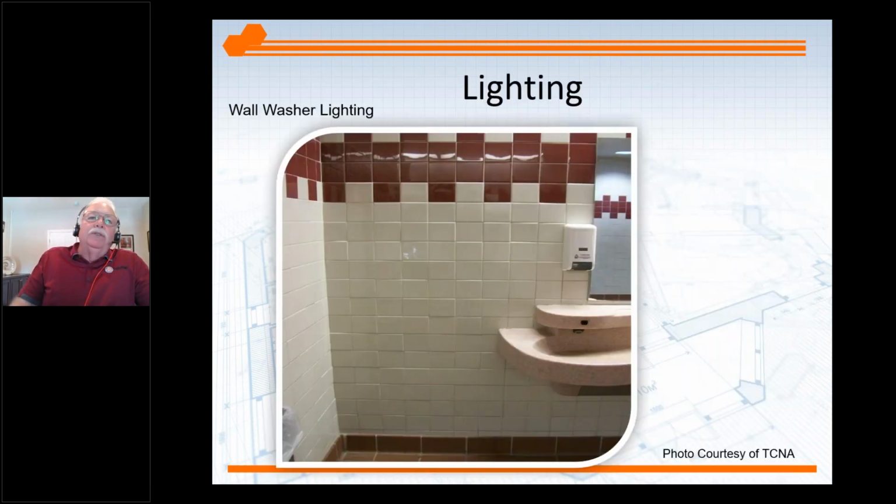Lighting also plays a huge effect. Wall washer lighting can cause a very good installation to look bad. We also should require that the proper lighting be there when they're installing tiles. I can't tell you how many jobs I've walked where you walk into the bathroom and they've got one little spotlight lighting up that wall for working on that whole bathroom. The wall washer lighting can actually cause a lot of ripple effects.